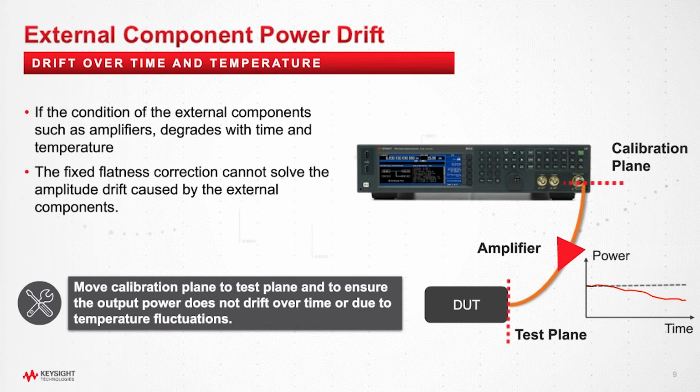The figure shows an amplifier between the signal generator and the device under test. The amplifier's output power degrades with time. You have to extend the ALC operation from inside the signal generator to the device under test input, the test plane.